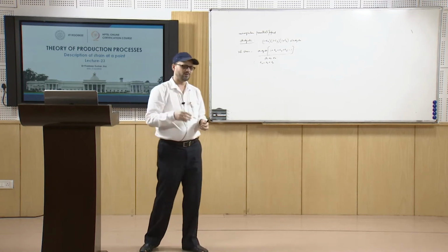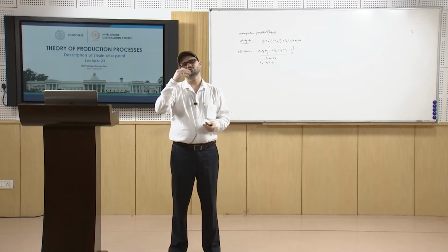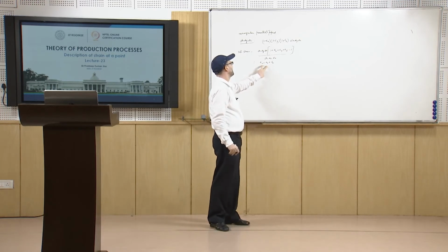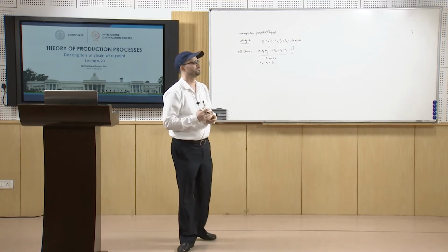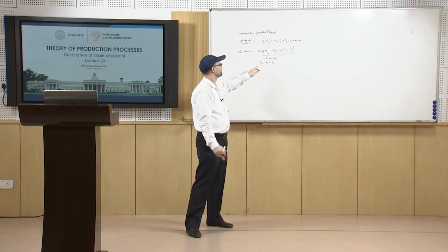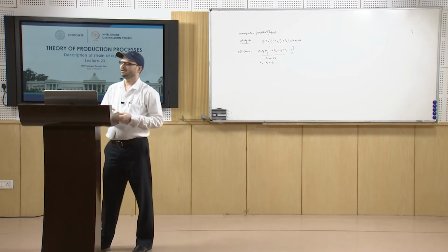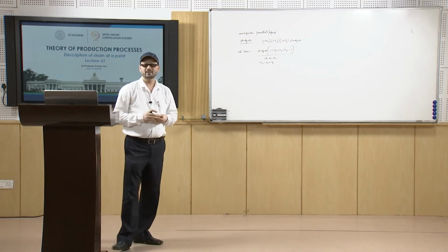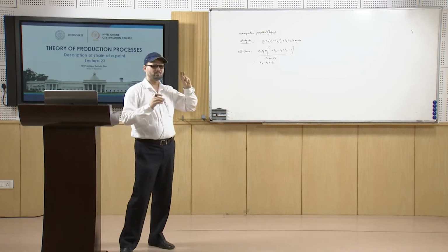In tensorial analysis, when finding the roots, you will see that this is the first strain invariant, just as in the case of the stress tensor you got the first stress invariant. This is also defined through the mean strain.